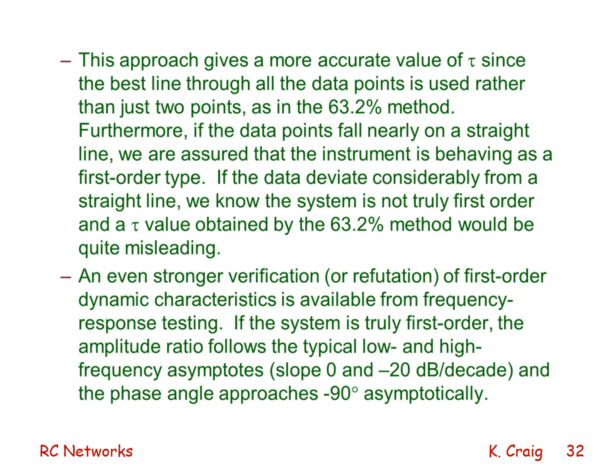As we will see, if the system is truly first order, the amplitude ratio follows the typical low and high frequency asymptotes. Slope of 0 at low frequency, minus 20 dB per decade at high frequency, and the phase angle approaches minus 90 degrees asymptotically.